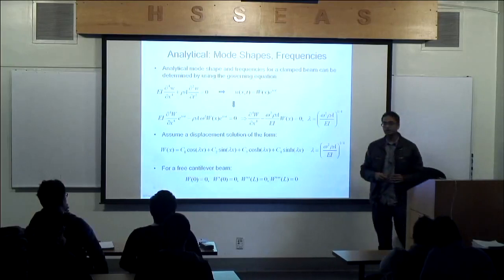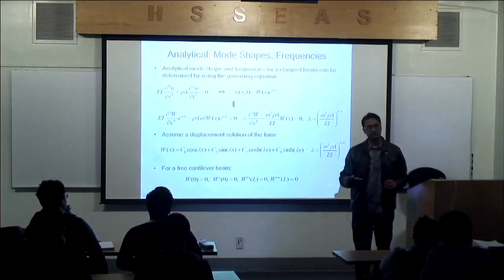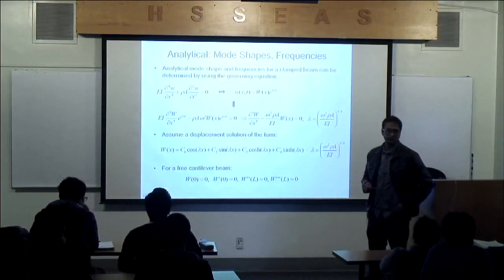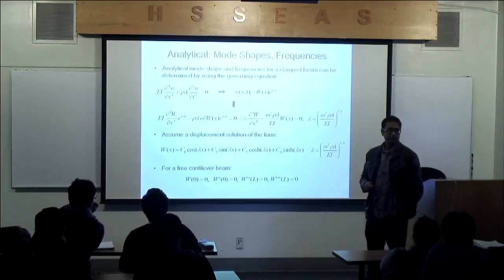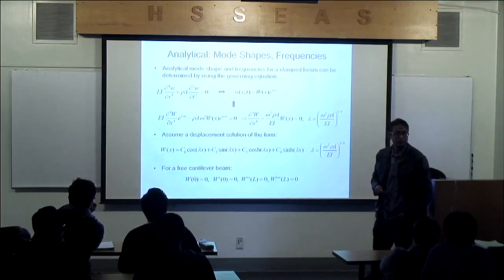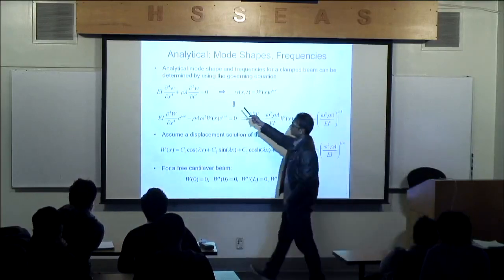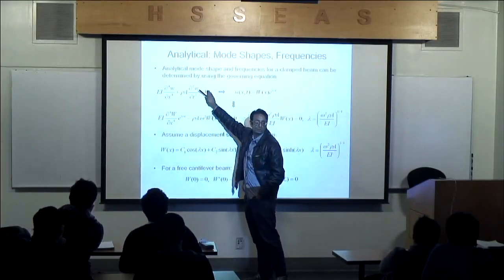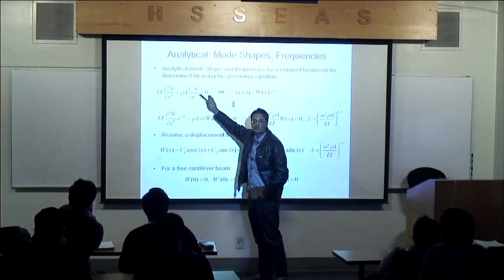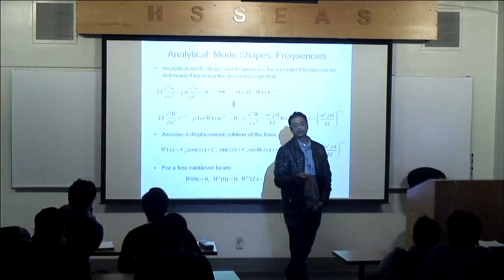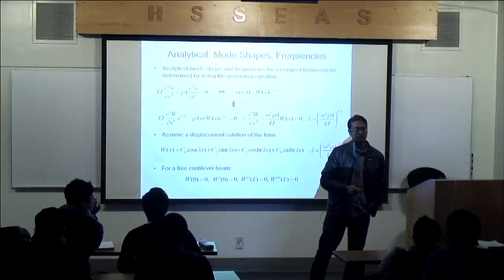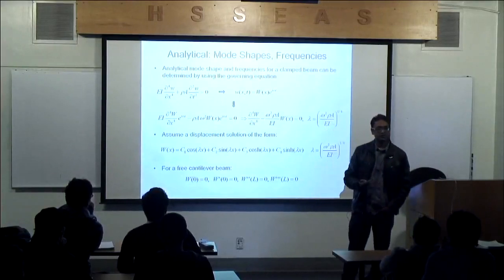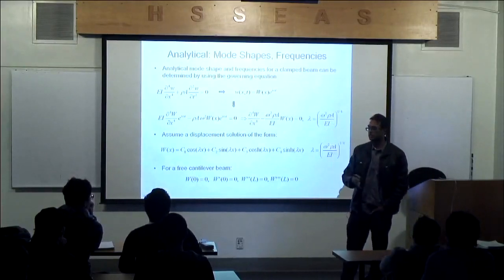So let's look at this a little more theoretically, because we need to understand where these dynamic eigenmodes and frequencies come from. If we know the equations of motion, and I have no forces applied, no natural boundary conditions applied, no distributed forces applied, we will call that a free vibration problem, because I don't have a load applied at this point in time.